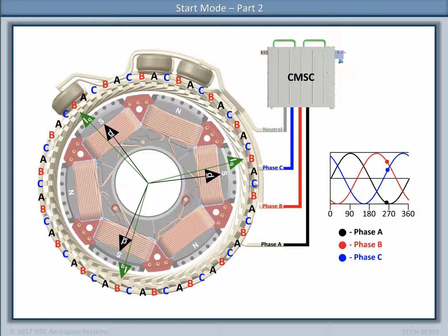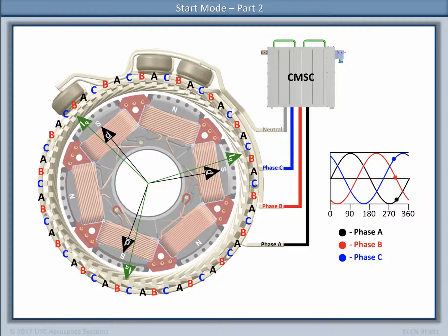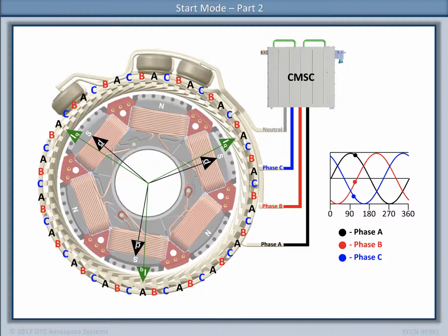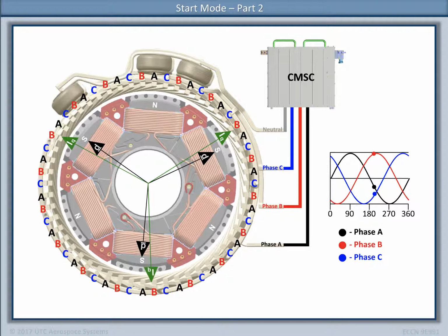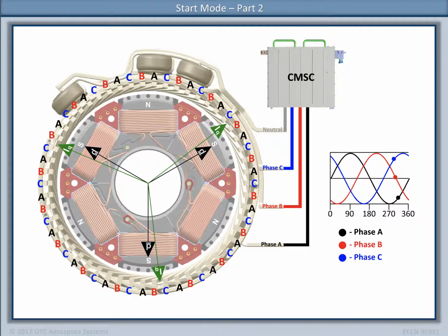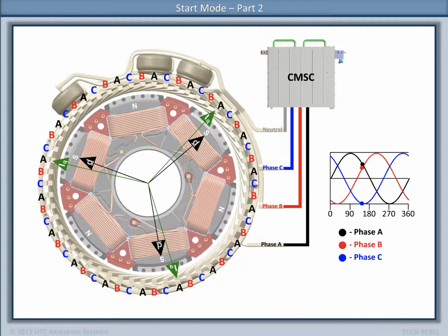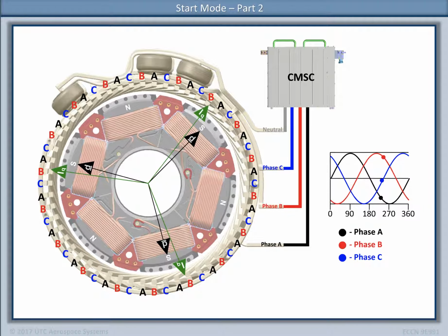The rotating 3-phase current creates rotating stator magnetic flux vectors by varying the stator current level of each phase, so that the rotating stator magnetic flux vectors always lead the main rotor magnetic flux vectors by 90 electrical degrees and always pull the rotor toward them.